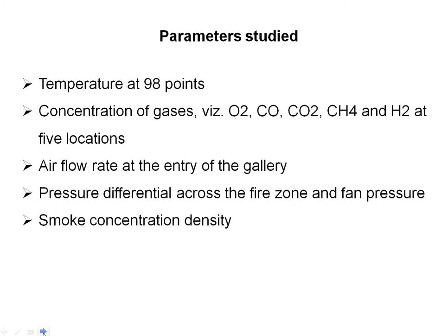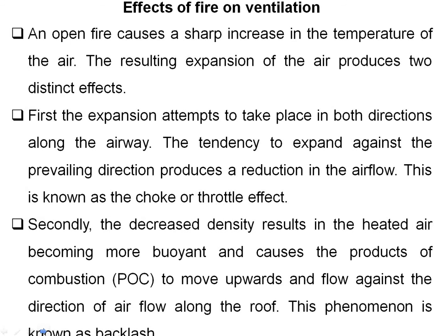I told you several times that the fire zone, fan pressure as well as the pressure difference are the most important things, and the smoke concentration density you may take. Smoke means there is no dilution of air. If you flow the air, then every gas will be diluted and no CO2, no CH4, no CO will be there. So smoke means there is a chance of CO, and carbon dioxide is also there, hydrogen may also be there, and other hydrocarbons are also there, okay, meaning methane, ethylene, ethane, acetylene, etc.